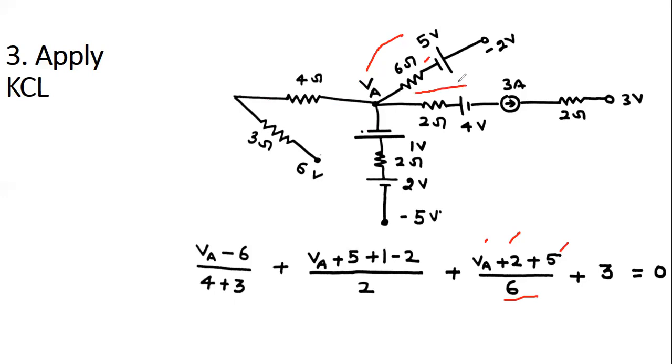And the current in this branch: because this is an outgoing branch and a current source is given, forget about all the voltage and current regarding the branch. There is a 3 ampere current, so consider this branch as 3 amperes, and these are all the 4 possible currents at this node, taken outgoing, and make the sum equal to 0.